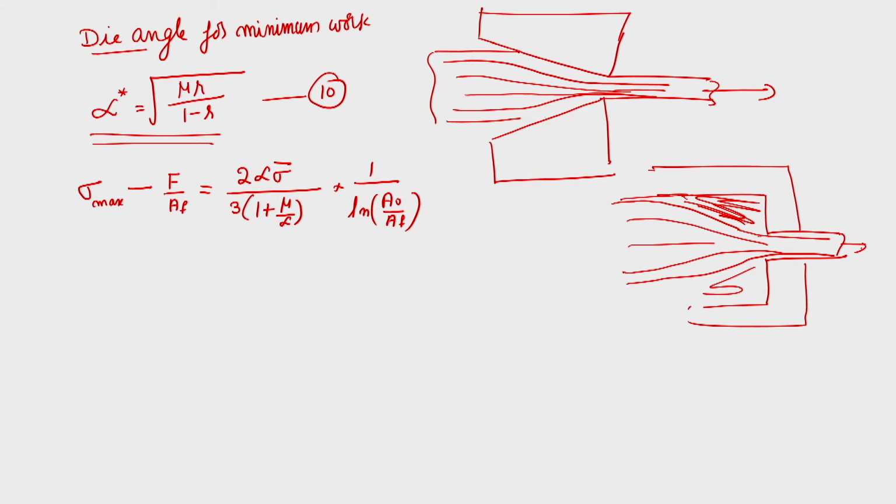What will happen is that at the center of the sample during drawing, you may end up with chevron cracking. So, a crack at the center will take place in the presence of tensile stress. If it is above a certain limit, it will result in center line cracking. It has the shape of a chevron. Okay? So, you know what a chevron shape is.